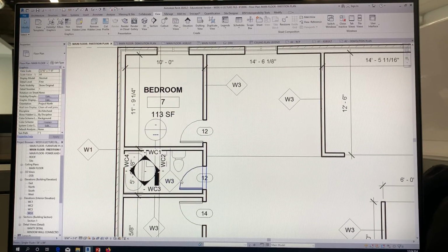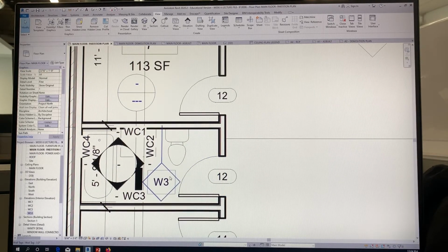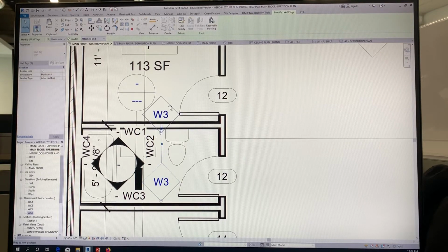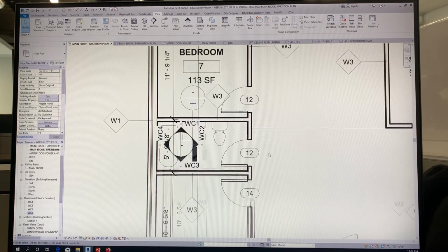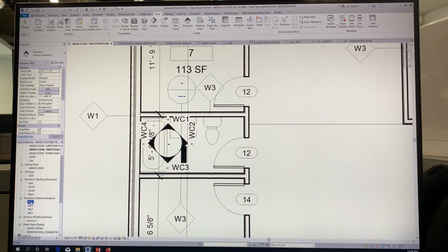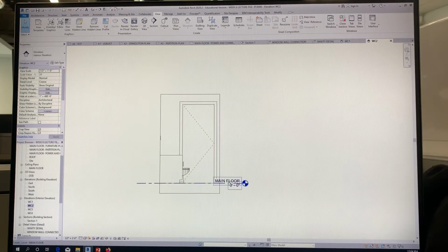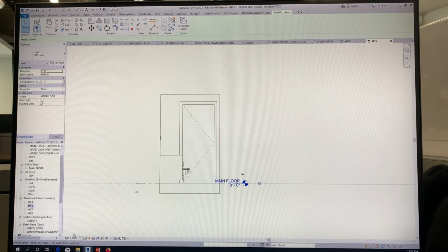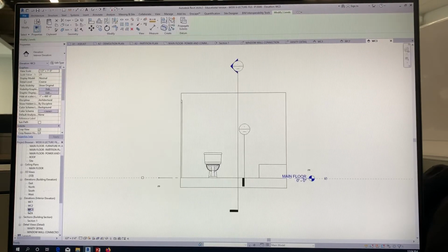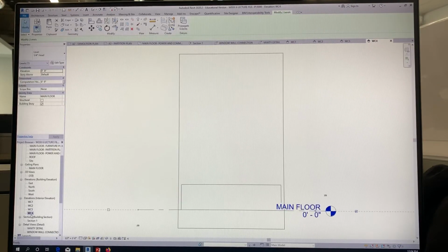Again, hopefully you'll have a lot more room in your washroom than I have here. Okay, I could easily move some of these things out here a bit. Alright. So now there's all my different wall elevations. Okay, and they're all set at 1/2 inch. Double check, they're all set at 1/2 inch equals a foot.